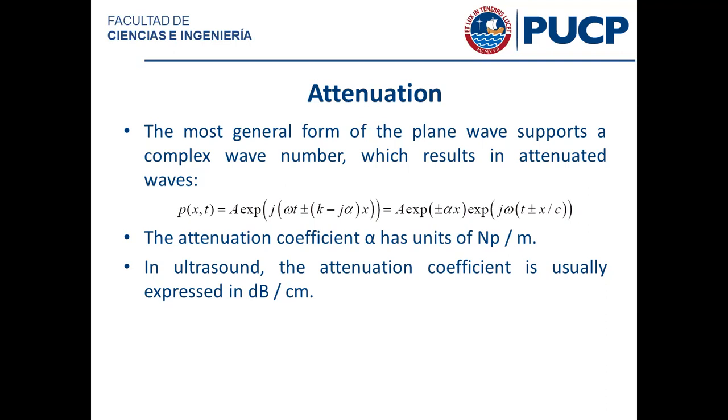So you want to use a high frequency. In practice, if you could, you would go for the highest frequency you could produce. But unfortunately, that also implies that you're not going to be able to go very, very deep, because the higher the frequency, the worse the penetration. Okay, just remember that, and we'll talk about that afterwards. Any questions up to this point?